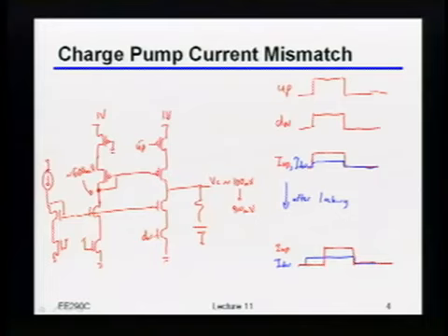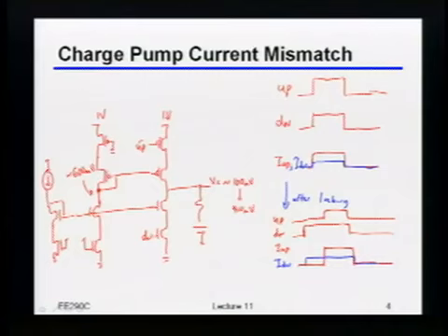Down always has to arrive first, right? Because if it doesn't arrive first, there's no way for you to get this waveform. So again, we can draw the up and the down here. That says down shows up like this, and up shows up like that. So in other words, this charge pump current offset is actually translating into static phase offset at the output of the PLL, right? Because there's no other way for the PLL to lock or get those charges to be balanced except to skew those pulses against each other.